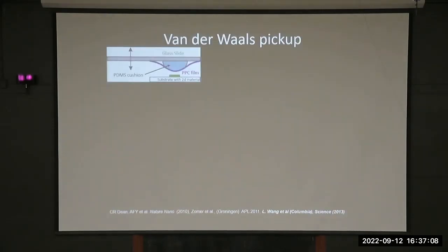So how do we do this? The experiments I'm going to tell you about are all made more or less in the same way. We make devices where we have 1 or 2 or 3 or however many layers of graphene that are the thing that we want to study. But we also want to be able to control their density, so how many electrons are in them, and we want to be able to control this electric field. So to do that, we need to add gates to them, just like in a field effect transistor. You need a gate that you can apply an electric field with, usually on the top and on the bottom. And by controlling those, you can control the electric field through it and also the total density just by charging that capacitor.